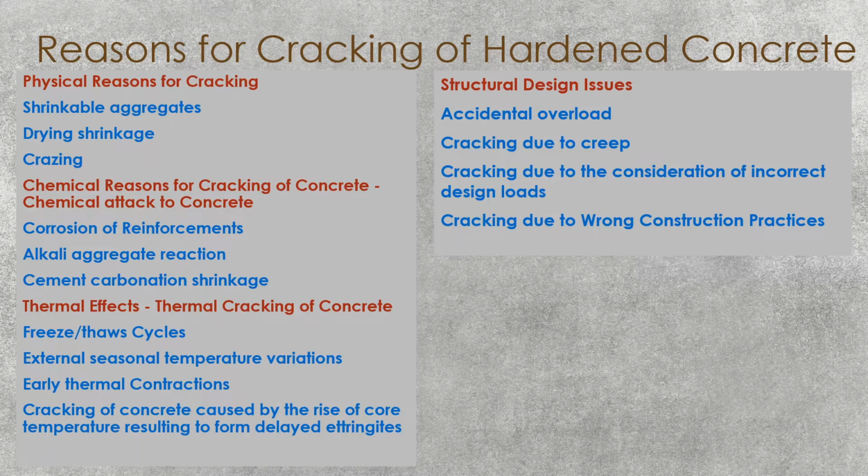If you talk about structural, initially this cracking will be considered as a warning. But if the crack width increases, there will be certain issues in structural stability. The structure could fail. So if you see these kinds of structural cracks, you may have to take immediate action. There may be bending cracks, shear cracks, torsional cracks, or any other structural cracks. You have to attend to them seriously and take necessary actions.